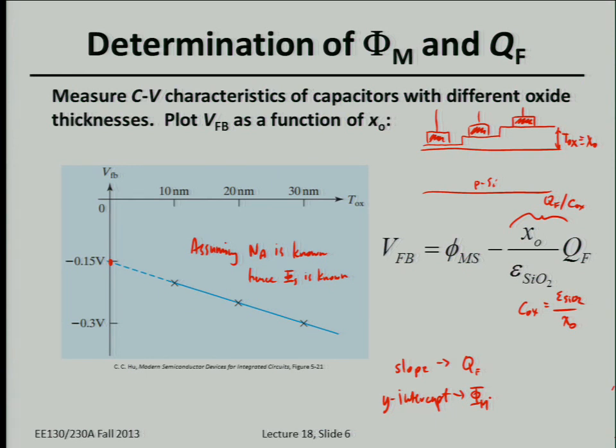more than 10 years ago when the industry and researchers were trying to develop new gate stack materials for CMOS capacitors, CMOS transistors. So, the last part of today's lecture is about poly gate depletion. So polysilicon was the preferred gate material for many years because polysilicon can withstand very high process temperatures. Okay, so the way you normally make a MOSFET is you define the gate electrode, and then you form the source and drain regions in a self-aligned manner. So the source and drain regions are perfectly aligned to the edges of the gate. So you actually have a nice transistor formed this way.